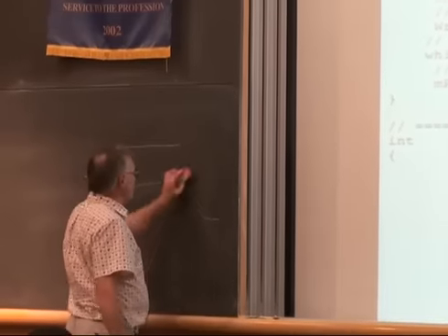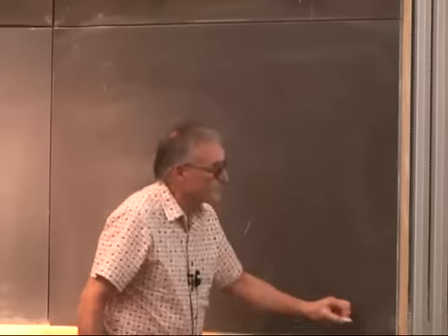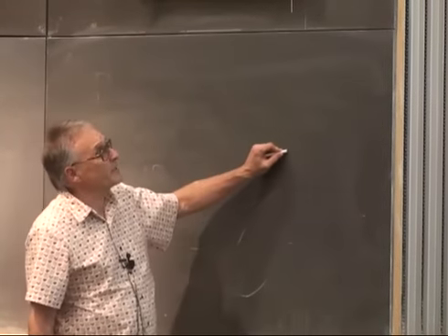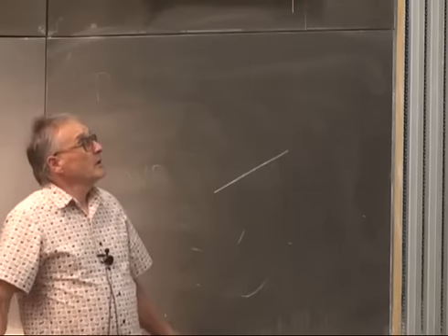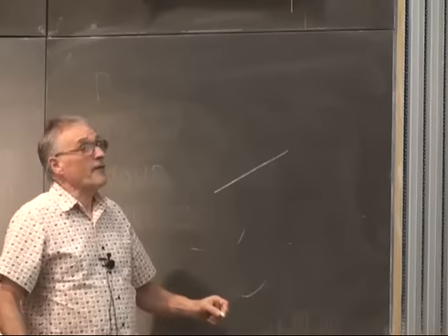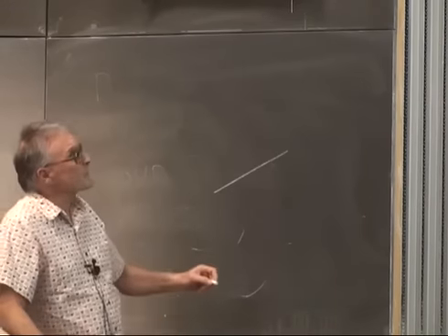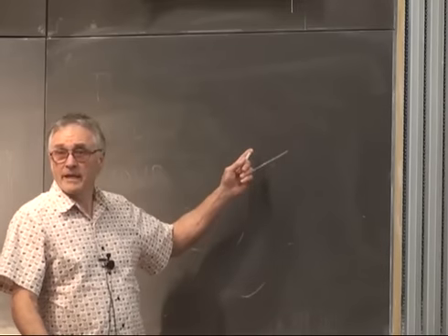DAC data is an int, a 32-bit int. So if it starts at 0, it counts up until it gets to FFF, which is 12 bits of ones. And then the AND: it overflows to the next bit.